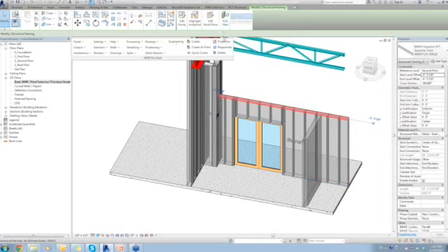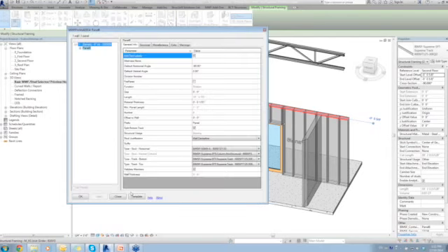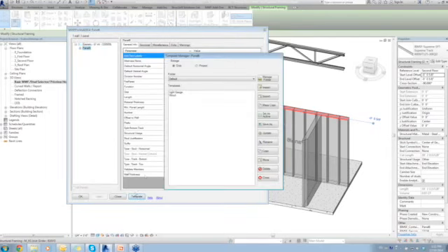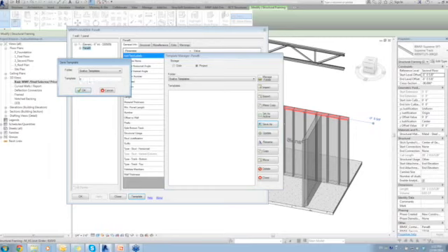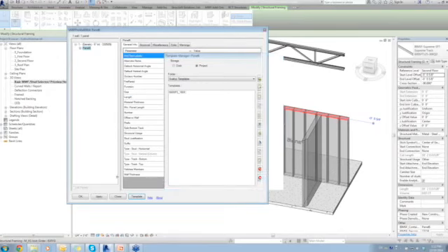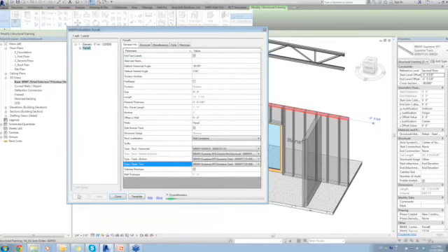Utilizing the power of MWF, I can now, again, open this template's properties, and I can save this template for future use. So I can base other panels I'm going to be creating today off of the properties of this panel. So we can call it something like 600 SFS, and I know my stud spacing is 16 on center. So I give this template this name, I can close it and continue.